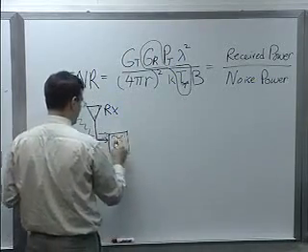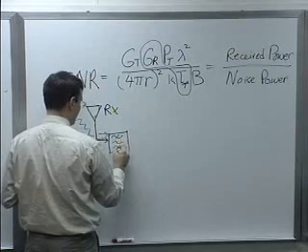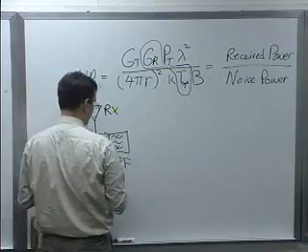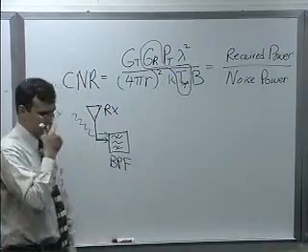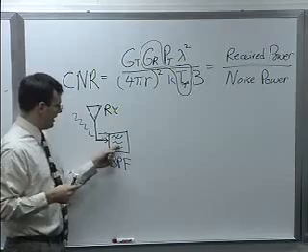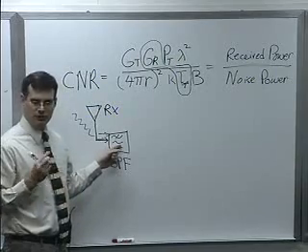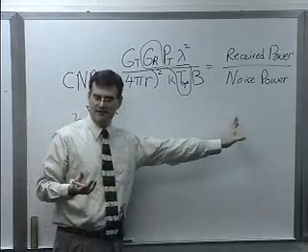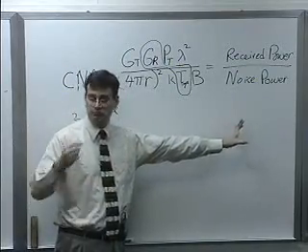You can sometimes get away with an LNA, but a really good RF designer will always put a bandpass filter as the first stage. The reason is not necessarily to clean up your desired signal, because you can do that later on in the RF chain, and you can do it better.